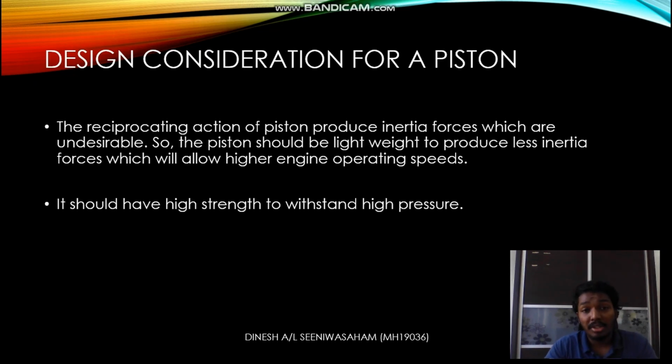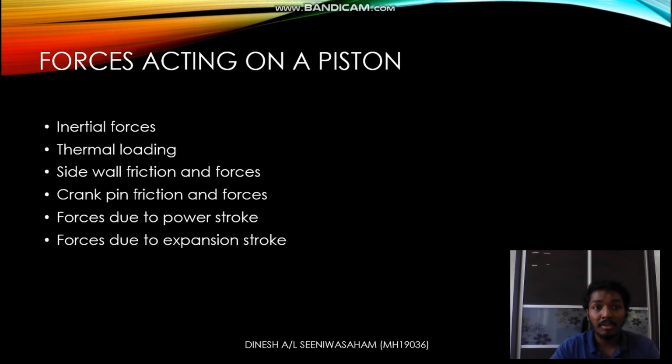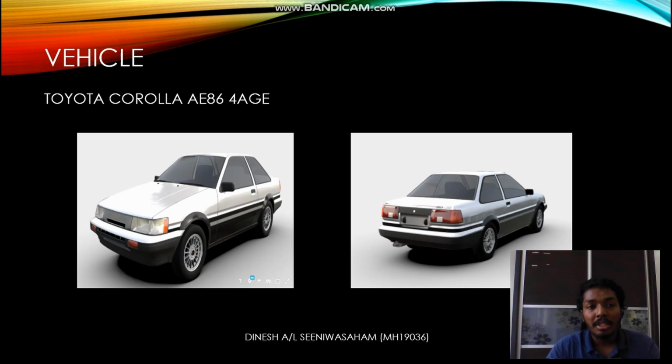So, design consideration for a piston. The reciprocating action of the piston produces inertial forces which are undesirable. So, when we design a piston, it should be lightweight to reduce the inertial forces, which will allow higher engine operating speeds. There are several forces acting on a piston, such as inertial forces, thermal loading, sidewall frictional forces, and many more. And for the project, the vehicle we chose is the Toyota Corolla AE86 4A-GE.